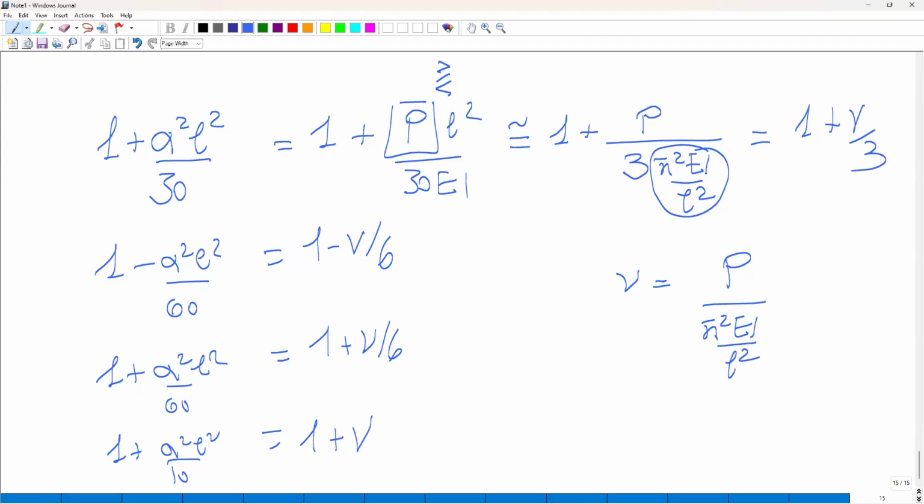Okay. And you measure the deflections, and what do you do? You make your own calculations and see, okay, according to my calculations, this deflection should be this. I measure this, but you also go to the design report and see, okay, the design engineer has said that according to his calculations, the deflection should be that. So you have 3 numbers to match.